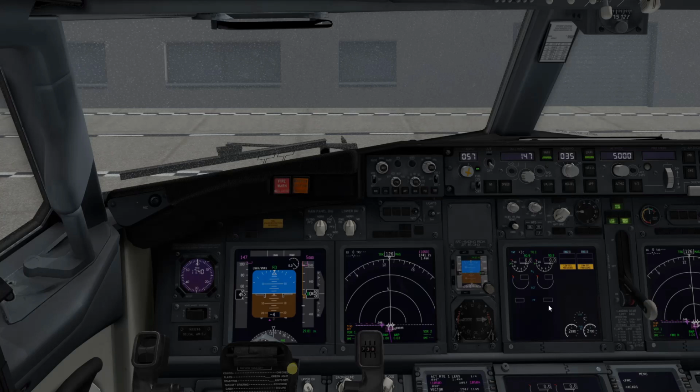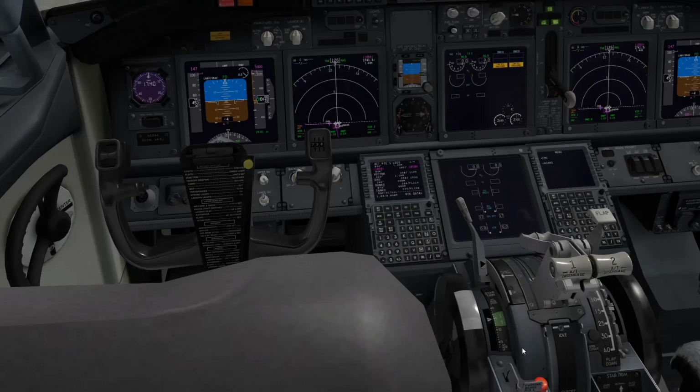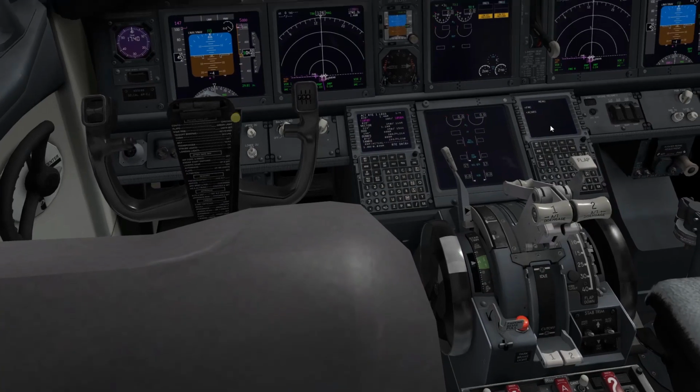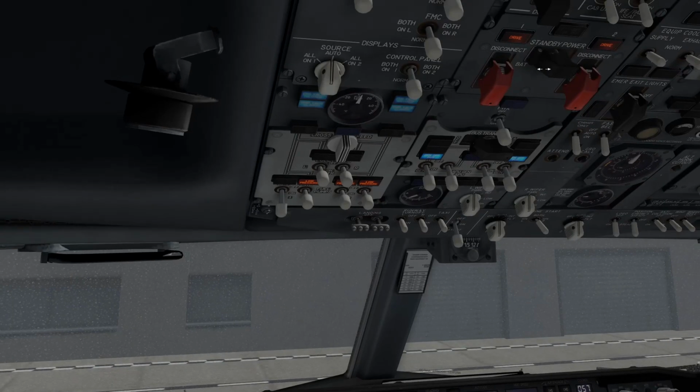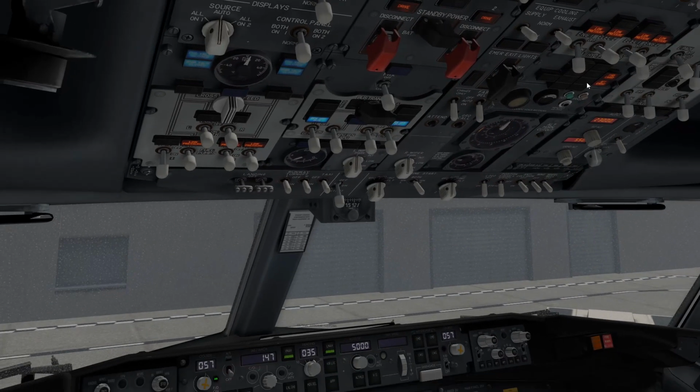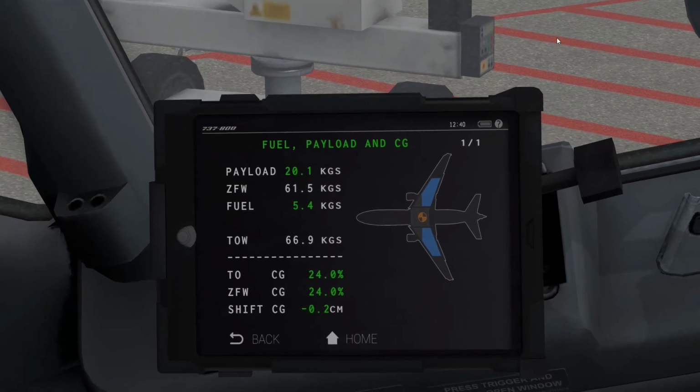Alright, so all doors and hatches are closed. Ready to connect. While he's connecting, we'll run the before-start checklist. Park brake set. It is set, the lights on, and we have sufficient brake pressure. Windows, doors. Okay, we still have two doors open, the forward and aft cargo doors. We're going to have to get those closed.